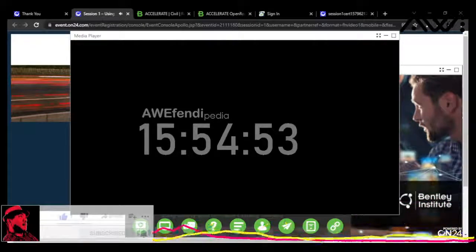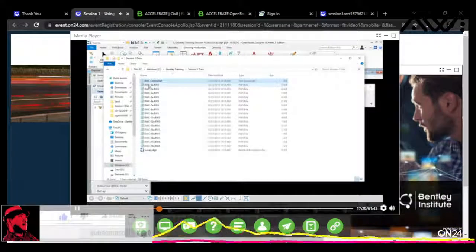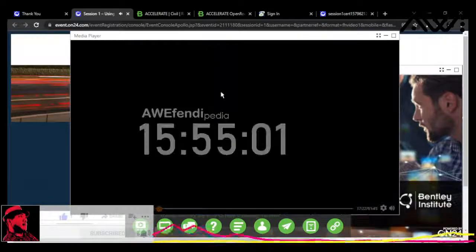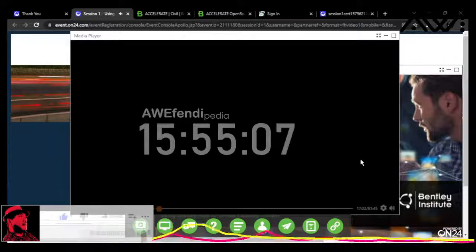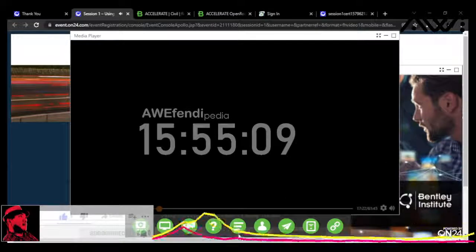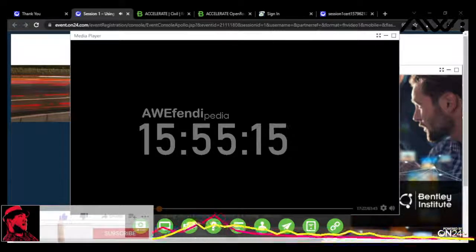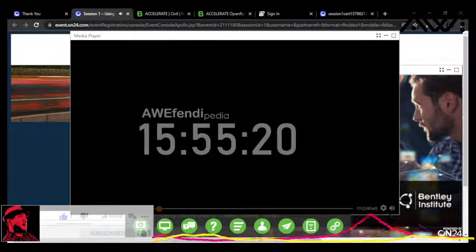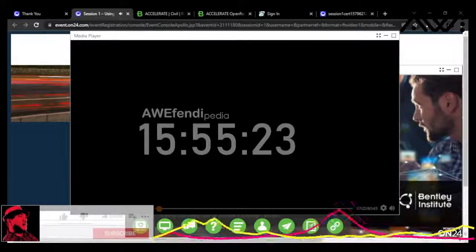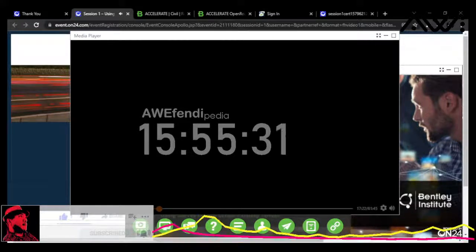The rest of the files that we will import are RW5 files, so let's take a look at one of those real quick. These are the standard TDS format, but what I want to show is the type of coding that this user is using. We have an alpha feature code, and that feature code is before the linking code. So those are some settings I'm going to set up in the program when I get to it. And we can see that we're going to be using linking codes to link up all our shots. I have a shoulder here, and I have a separate string here, a shoulder 1.